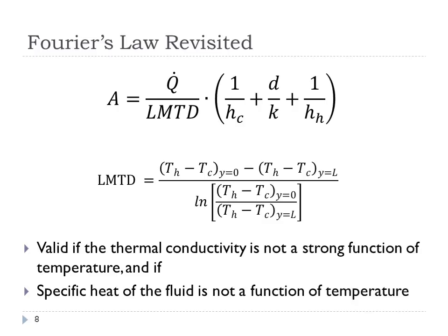When the differences are equal, you'll notice that this equation looks like it's 0 divided by 0. So you have to use L'Hopital's rule. And what you'll find is that the log mean temperature is just equal to TH minus TC, which is a constant in this case, as you would expect.